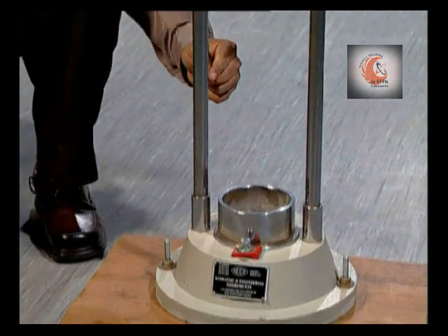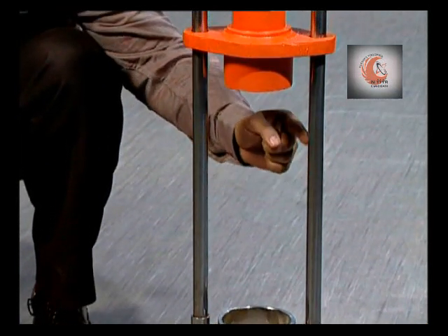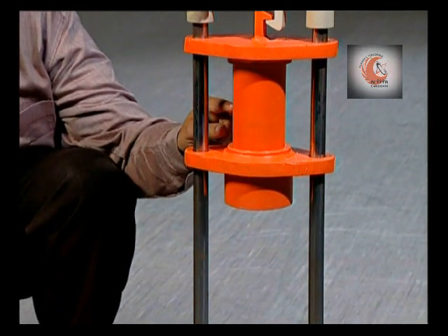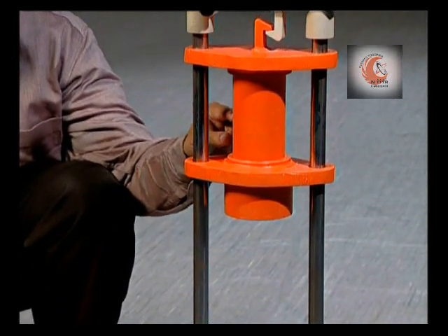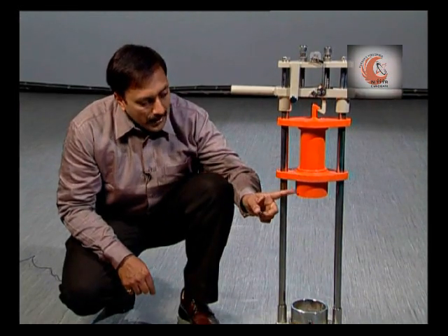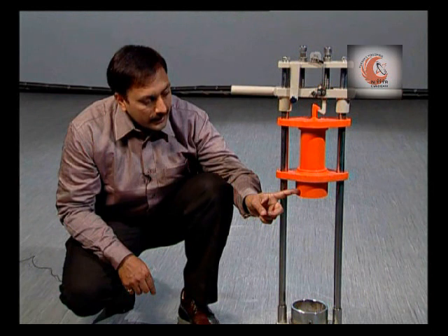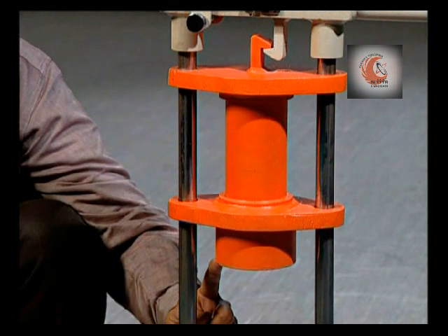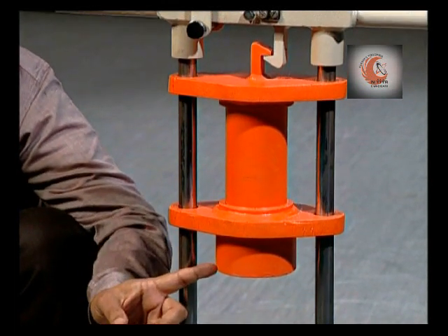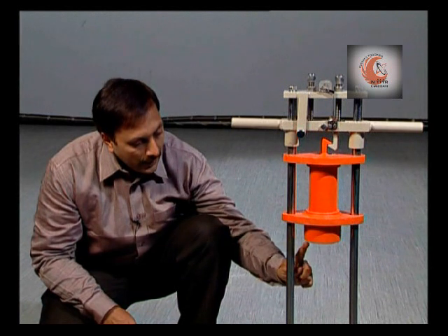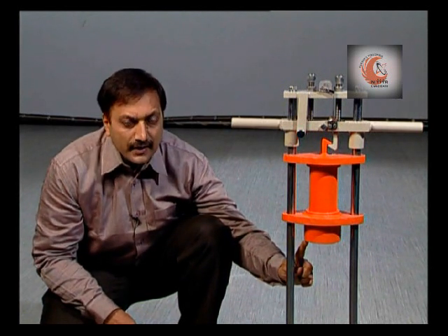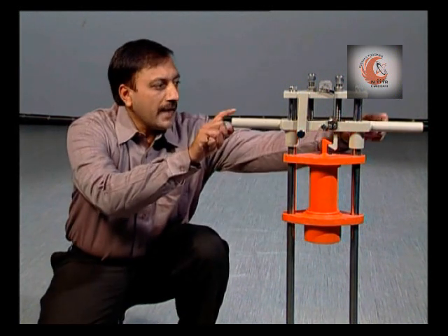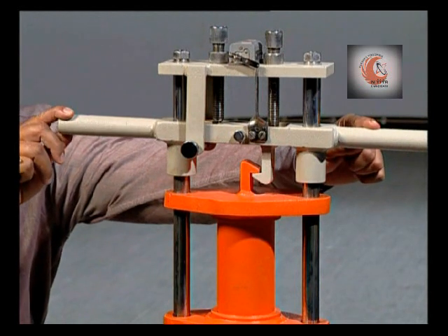It has two vertical guides which control the movement of a hammer weighing between 13.5 to 14 kgs. The bottom part of the hammer is cylindrical in shape with a diameter of 100 millimeter and depth of 50 millimeter. The lower end is case hardened with a chamfer of 2 millimeters. A lifting handle is provided to lift the hammer.